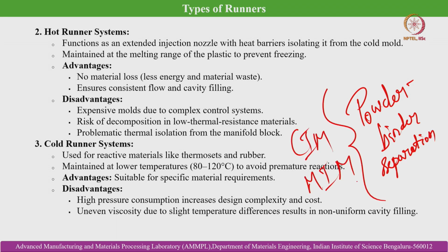As we have already discussed, in both of these processes we load the metal and ceramic powders with polymeric additives, and they facilitate the flowability of the metal or ceramic powders. Hence, because of the drag and the difference in viscosity, there is a tendency for powder accumulation in some regions within the component cavity, while in other regions there is a chance of accumulation of the lesser viscosity polymeric ingredient. That needs to be avoided, and that can be done by effective design of the runner systems.